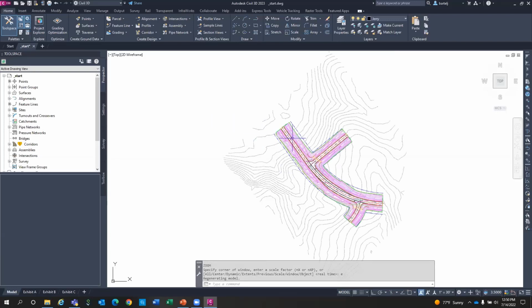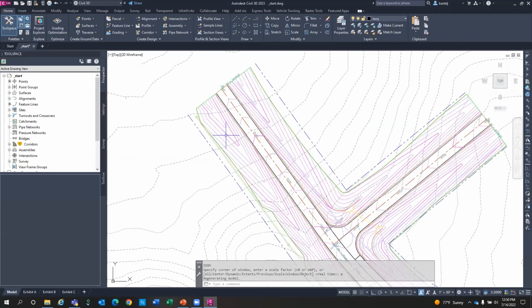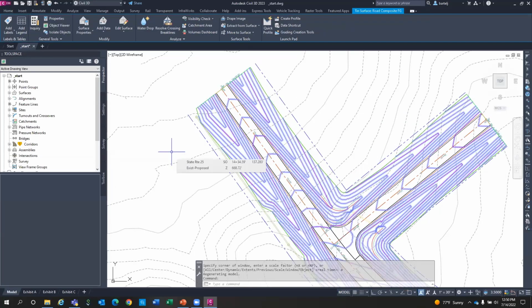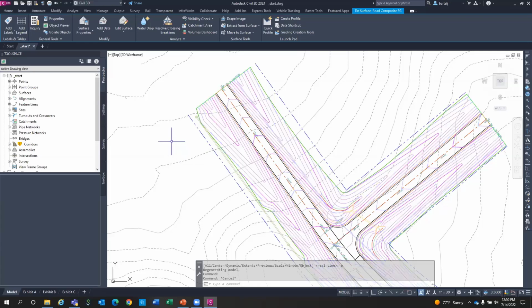Let's look at this. Now that this is turned on, I've got a surface here. I need to give this drawing to somebody. They don't need it as a surface because they're just running it in Core AutoCAD or LT or something else, but they need to see this as 3D polylines or just polylines, not as a surface. The way that I would do that is I would explode it twice. First time you explode it, it makes it a block. Next time you explode it, it makes it polylines.